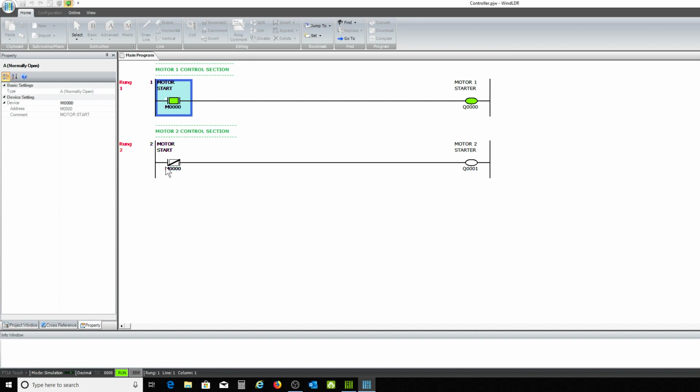When it's false, it's closed. In other words, when that bit is off, that's normally closed, just like a normally closed contact laying there on the desk with nothing hooked up to it. That normally closed would pass power through it if you hooked a battery to it and a little bulb. Same thing here. So the switch is off, normally closed, it closes back shut. Now you've got power going to Q1. I hope that kind of makes sense. Let's expand on this a little bit.